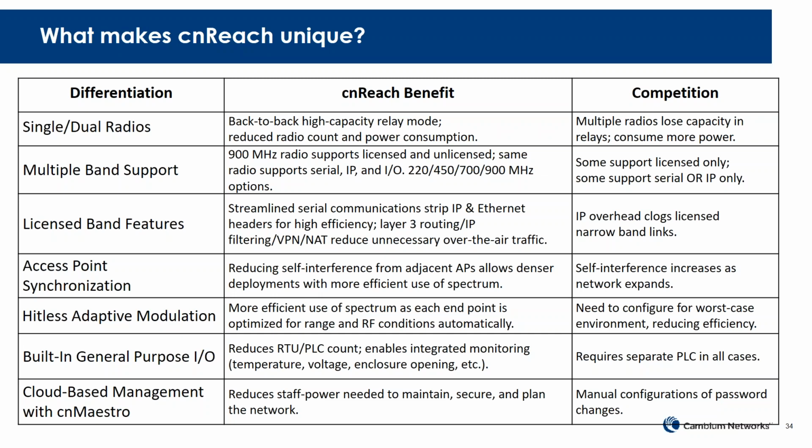If you just have a couple of APs on one tower, you can synchronize them by connecting the interface with a direct wire on that green connector from the picture. So it's that IO connector. If you connect those two pins together and you set one access point to generate sync and the other one to receive, all in the GUI, then they'll be synchronized.